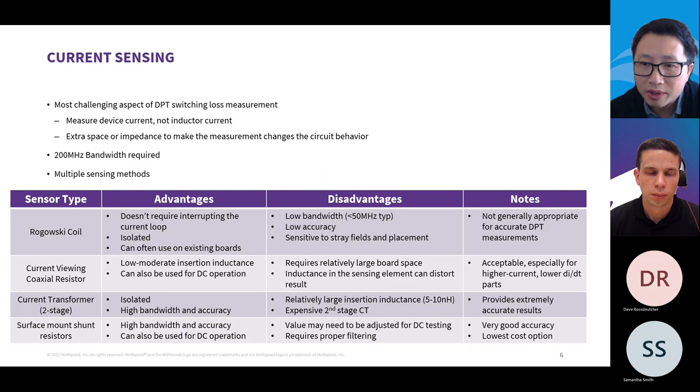Yeah, thanks for sharing the tip about measurement. We know that any little loop inductance in the probe setup will cause a big noise issue. And also, in order to make these energy loss measurements, you need to multiply and then integrate the voltage and current waveforms. However, you're using different probes to measure the voltage and current. Does the difference in the response or delay time of these probes really matter, and affect your results?